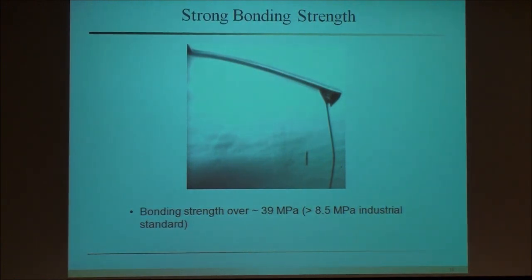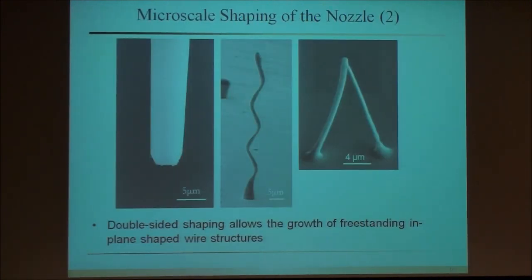And in terms of bonding capabilities, another issue we need to look into is the bonding strength. Since this is an electrical deposition process, the bond is extremely strong. So you don't need an extra way to increase the bond strength. And actually, the bond strength is much higher than this, because it turns out when we do measurements, this bond is electrochemically made. The other bond you have to fabricate through glue or something like that. So when you do pull-up tests, the first failure point is actually the glued bond instead of your electrochemically made bond.